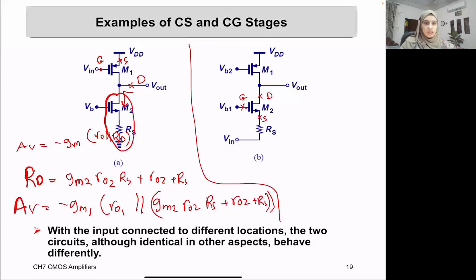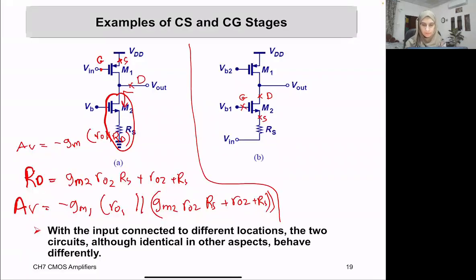Now let's find the gain of the amplifier. Okay, so the general gain of a common gate is GM RD, but we here have a source impedance, so not entirely Vn is applied at the source of the amplifier.